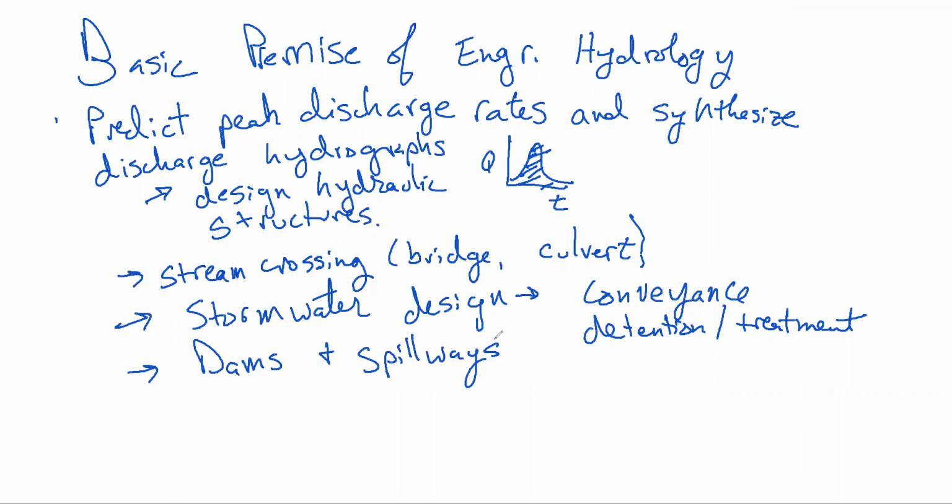Irrigation canals. I didn't talk about reservoirs specifically, but when you want to design a reservoir, typically these days, we don't build new reservoirs. Maybe we augment or expand the reservoir by building a higher dam because we need to store more water, maybe because we have less precipitation. There's a lot of hydrologic analysis involved in that. How much do we want to store based on our demand? How much do we have available, and what's the risk of it going dry? So reservoirs would be a big one.